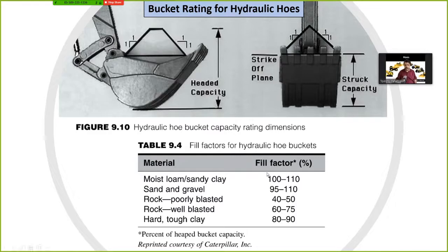That's why the fill factor could even exceed 100%. It could go up to 110%. And it mainly depends on the type of materials the machine is excavating.